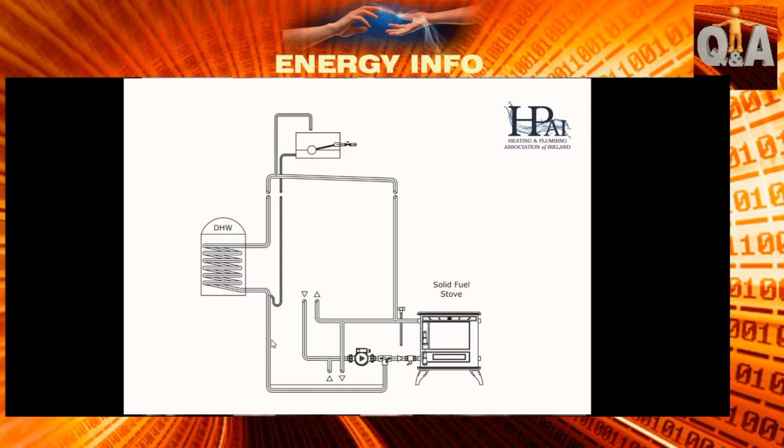It's critical that when you put pipe in an attic at any given time, you make sure it's insulated, and in my opinion, insulate the insulation. So in other words, double up, maybe even put fiberglass and polythene around the insulated pipe, but you want to make that pipe like a flask in the attic. But still that system has the dilemma of the hot water reversing back out of the cylinder.